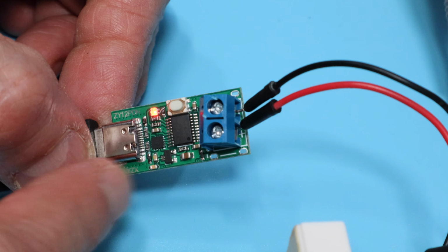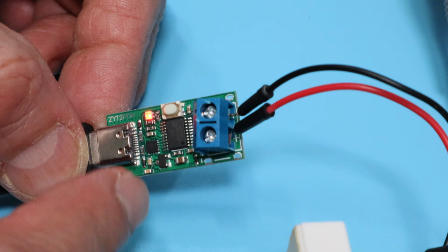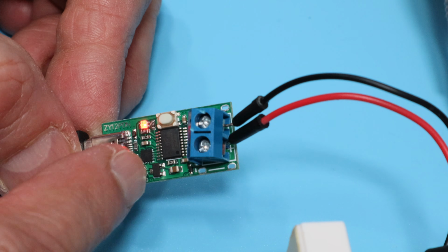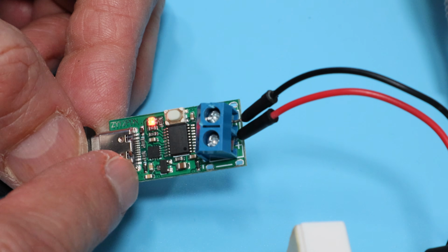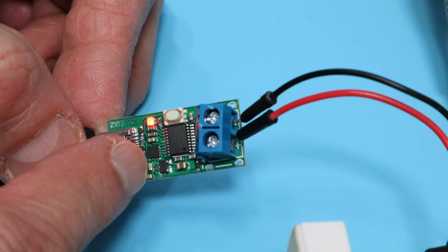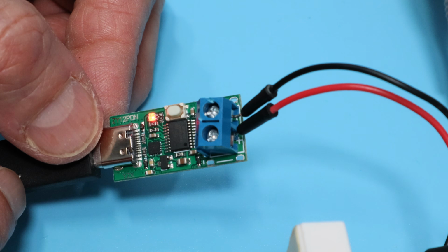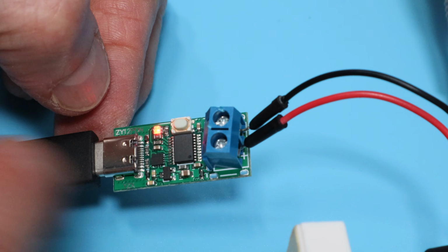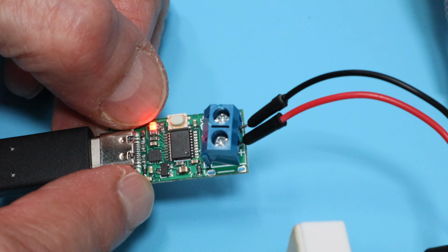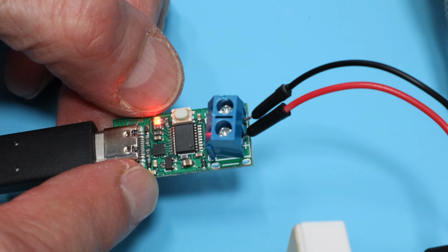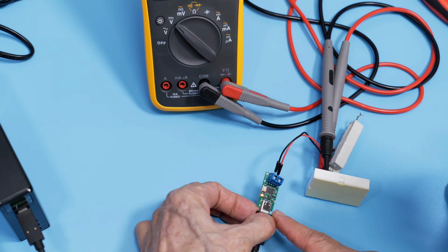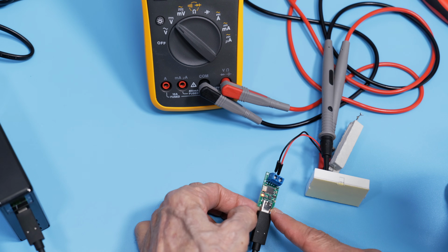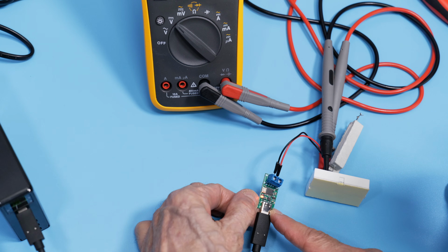Now, one thing that I noted earlier was that when you first plug this in, it's always going to revert to 5 volts. If you want to set it to a different voltage, you need to go through the procedure I described, where you take out the USB-C cable, hold the push button down, put the cable in, you'll get a flashing light over here, and then you can cycle to a voltage, and once you pick that voltage, it'll be its permanent voltage. But otherwise, it's a pretty easy module to use and a great way for powering things with a USB-PD power supply.